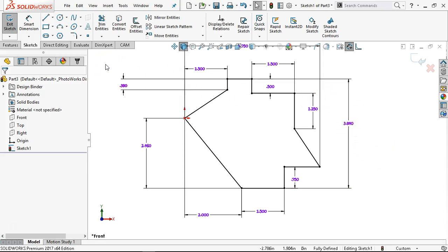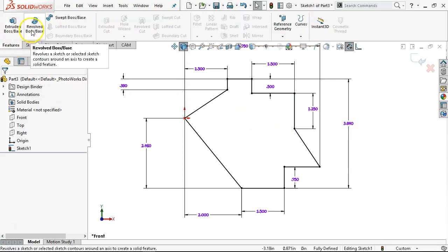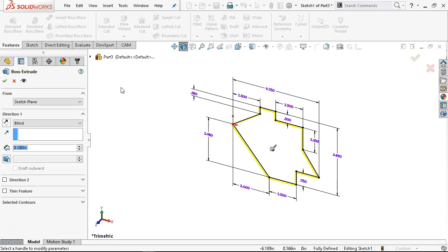It's for creating the part. And as I started to say, this is basically a process of elimination. Get something related to the origin. Get your geometry in place. Start adding dimensions. Pay attention to the relations. And as you build in the relations that you can identify, then you switch over to dimensions. You get as many dimensions in as you can. And if it comes down to 1 or 2 blue dots or 1 or 2 blue lines, that's where you start dragging things to see how they react and what you can do to bring it to be fully defined. All right, and then this one is 0.6. And OK.